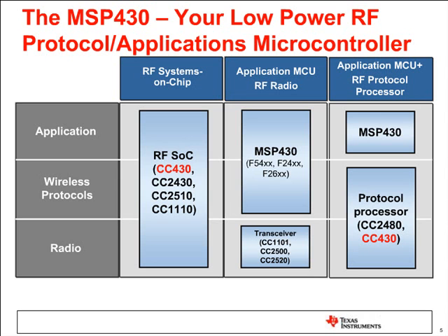In the past, we've had two-chip solutions with the MSP430, where the MSP430 is connected to another SoC. In the past, we've had, for example, the CC430, which has the integrated Zigbee, right? And you have this very small footprint interface that just lets you configure what is essentially a Zigbee black box. And so that would be the protocol processor. And the CC430 does fit that mold quite well.